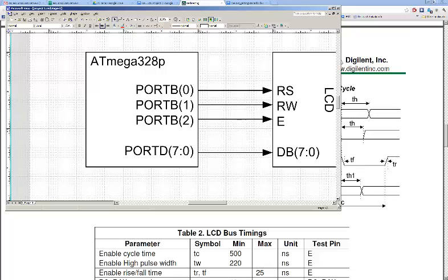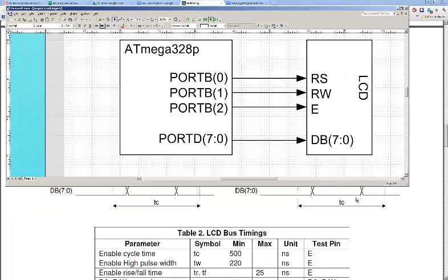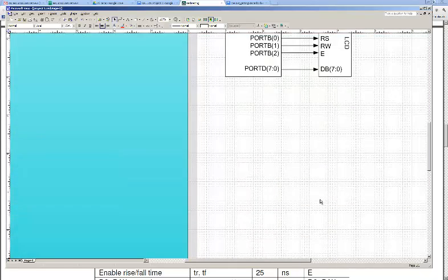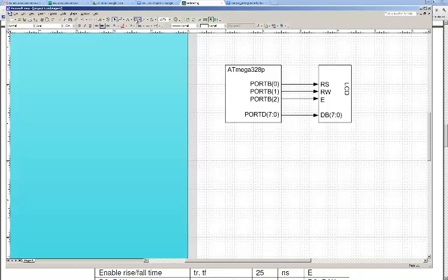And then I'll shrink this a little bit, and then I will open up a text box here so I can type on this thing. And what I'm going to do now is maybe write the code for this. The first thing we need to do is set up port B and port D as outputs. First DDRB, since the data direction register, if we set that bit within port B, DDRB, it's going to be an output if we set it to 1.